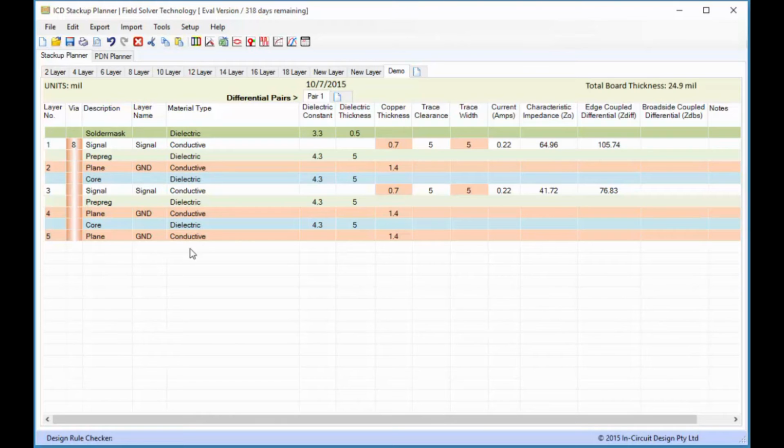And we don't necessarily want to have a bunch of different pipes that go, let's say, from 1 to 3 and 3 to 5, or actually it wouldn't be 5, but let's say 3 to 6. Some of them aren't even manufacturable anyways, and some of them are going to lead to signal integrity problems, and we don't necessarily want to go down that particular path. One of the things that this tool is going to allow you to do is to set up stackups and vias any way you see fit. But again, you've got to bring them to the manufacturer, your fabricator, to make sure that what you're putting together is manufacturable. Okay.